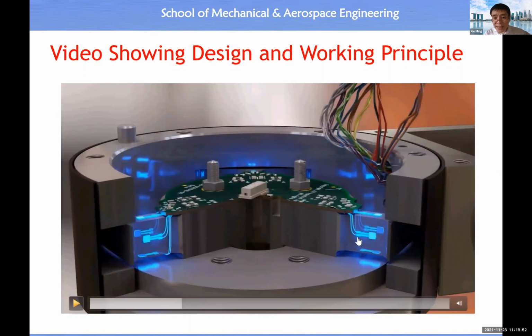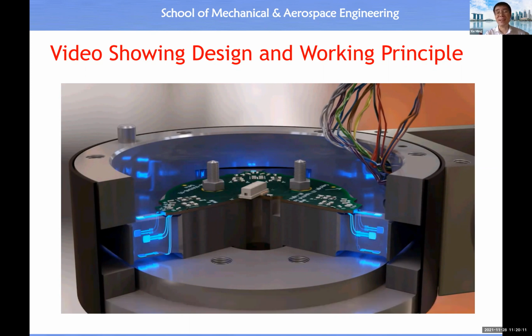And eventually here you may see, because each beam has 4 faces, then for this version, on each face we have a strain gauge. So that means in total we have 3 times 4, 12. All right, so that is in practice, but in theory, for simplicity, we can say for this beam we only have 2, this one has 2, this one has 2.